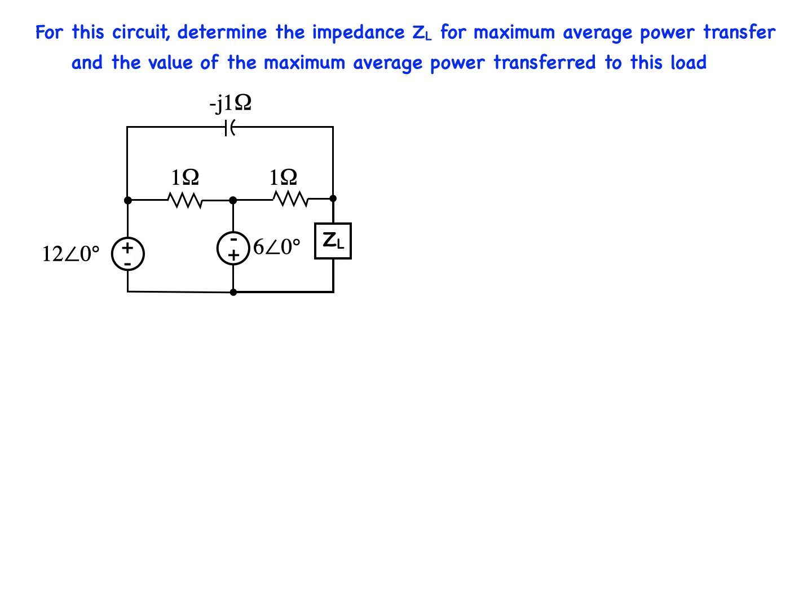The open circuit voltage VOC can be determined from this network, which, by the way, is the Thevenin voltage VTH. This open circuit voltage can be calculated in a number of ways. For example, we can start by computing the current I. The solution is not at first obvious. So in order to calculate the current, I'm going to disregard VOC for the moment and rearrange the circuit like this.